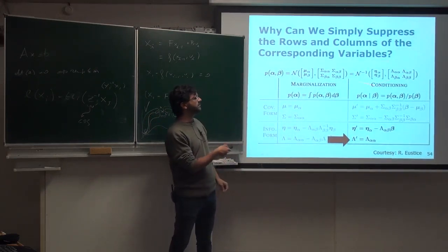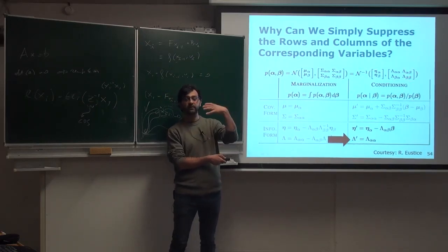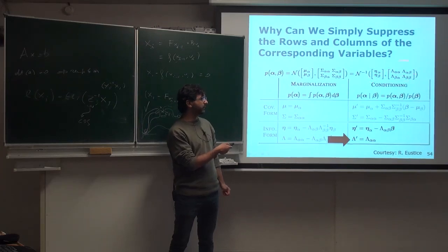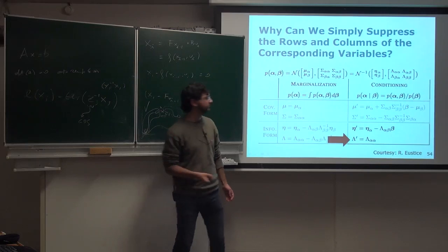And what we are saying is that inherently our distribution of the robot poses is a Gaussian distribution, which is modeled using not the moment formulation, but the natural formulation. So we have the information vector and the information matrix.